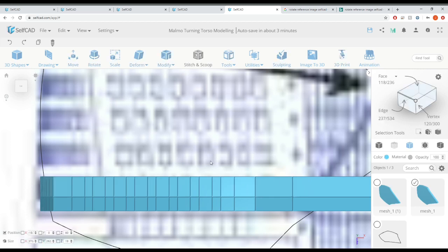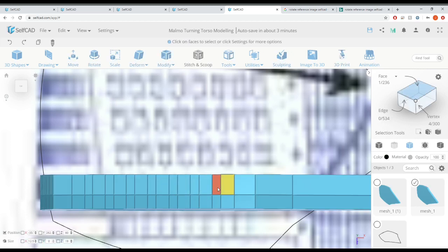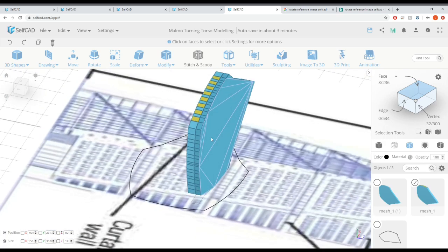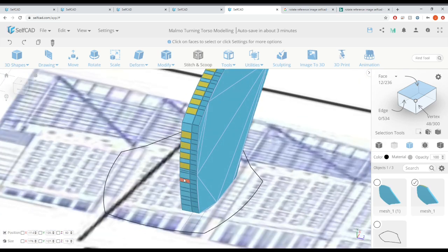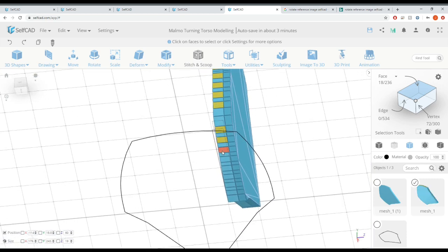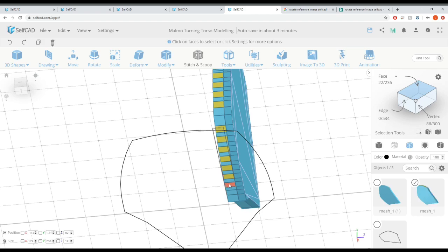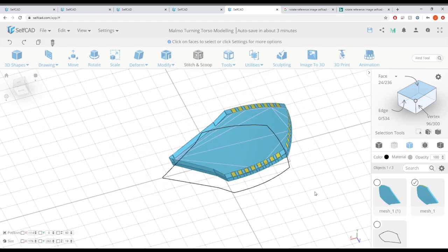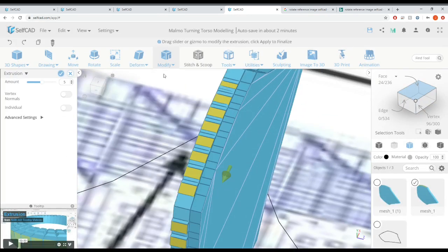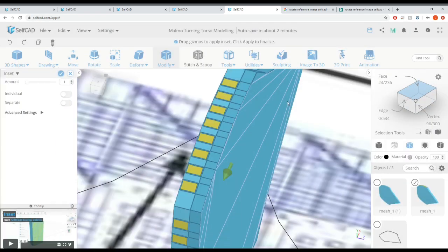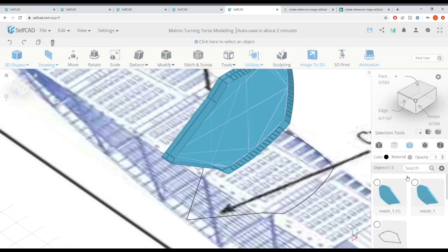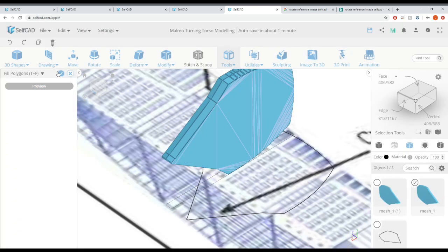And now the next thing we're going to do is start to select these windows and prepare them for our next stage of creating window frames and also extracting the glass within them, which will be useful later, so that we can apply a transparency material to it and the building reads much better. You've got windows, you've got solid panels. So I've chosen the wrong extrusion tool, but that's fine. We'll just go back. And now we've got inset at 1, which we just have to remember. We're going to use the same for everywhere.